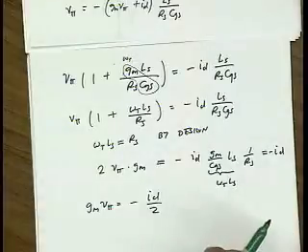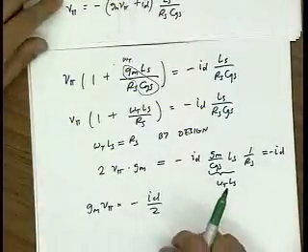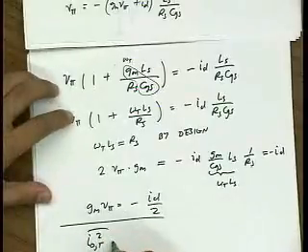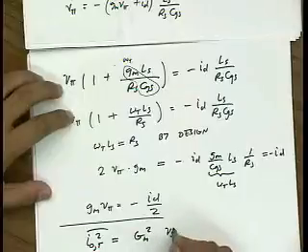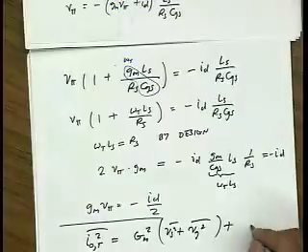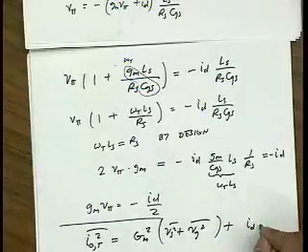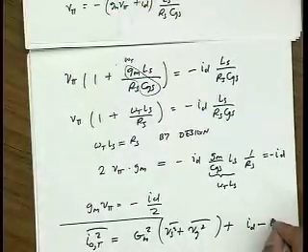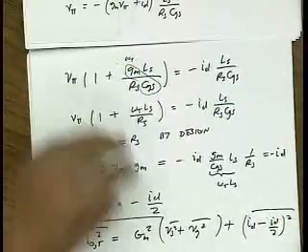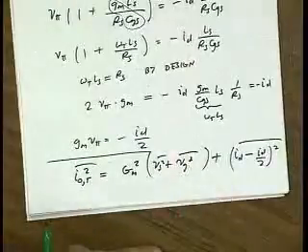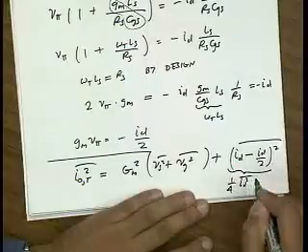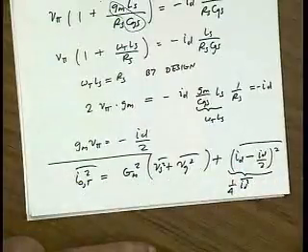Okay, so now if you think about it, I know exactly all the noise contributions. I can now say that the total noise contribution is Gm squared times the source noise, gate noise, plus drain noise minus drain noise over 2, right? RMS value. In other words, 1/4 of the RMS value of the drain noise ends up at the output.